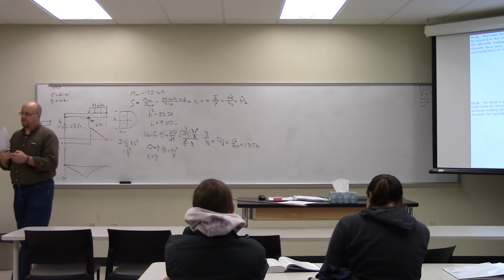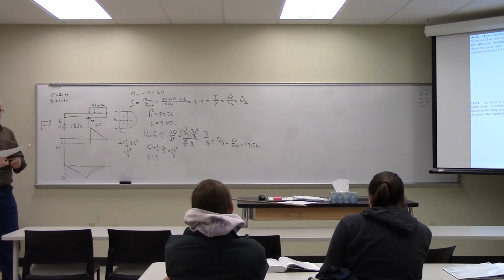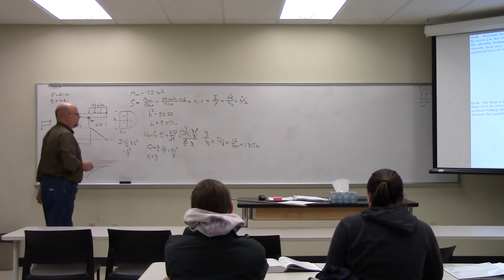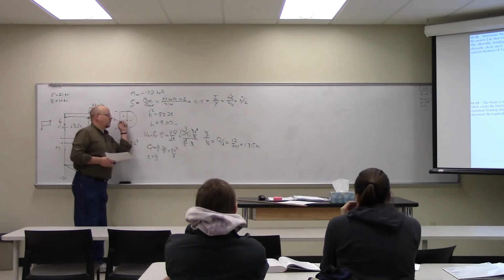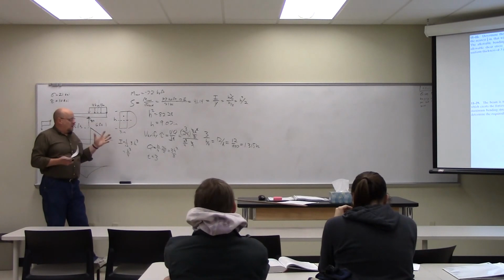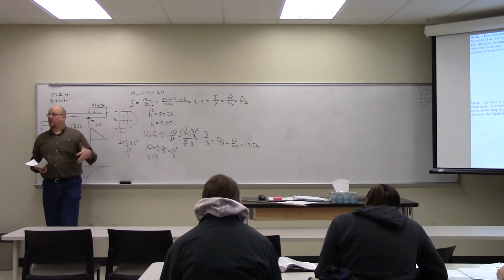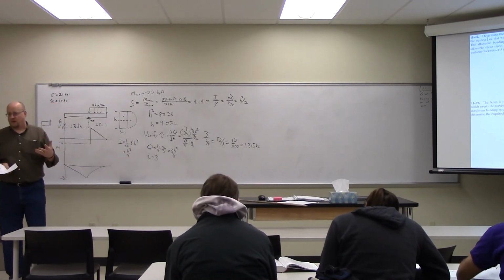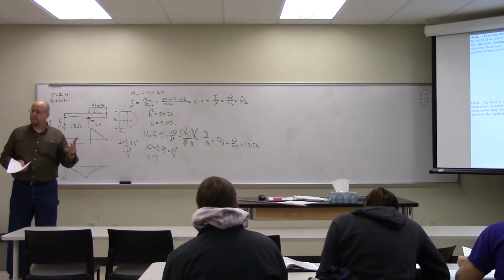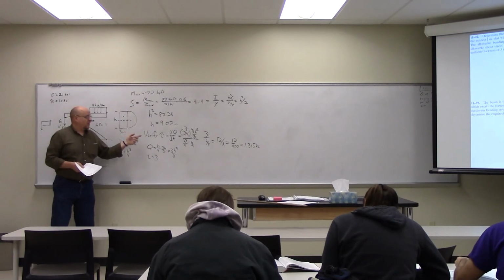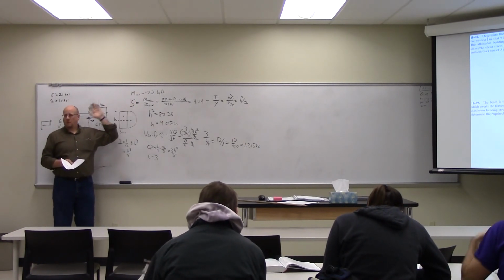Does that make sense? Okay, so I had to use the full value here because it was not a wide flange beam. But otherwise, much more straightforward. And the nice thing about the approximation is that for a wide flange beam, it's much more complicated to calculate Q for those things because the values are not even, not uniform.